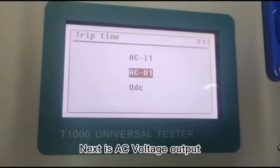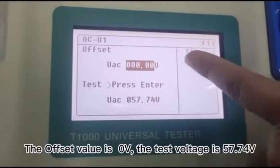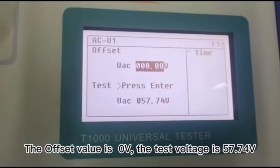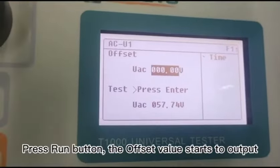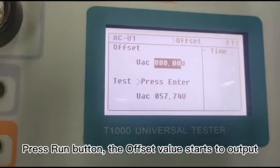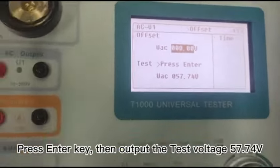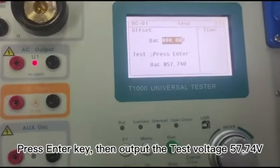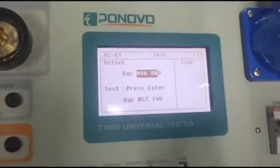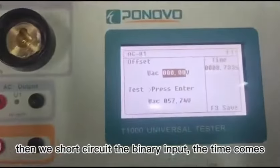Next is AC voltage output. The offset value is 0 volt. The test voltage is 57.74 volts. Press Run button. The offset value starts to output. Press Enter key. Then output the test voltage 57.74 volts. Then we short circuit the binary input, the time comes.